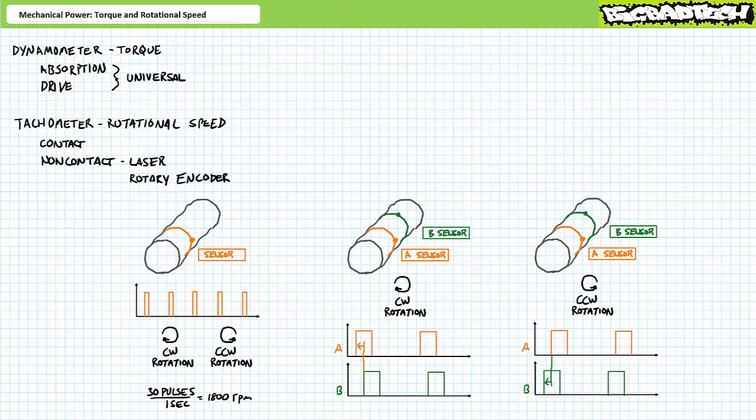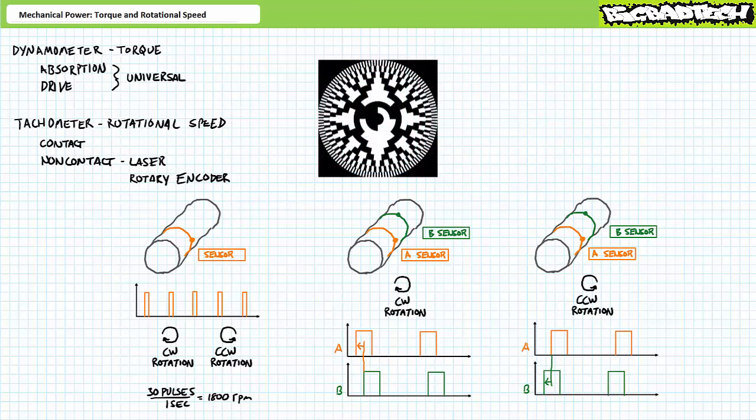There are varying levels of complexity of this type of rotational speed measurement, and is sometimes referred to as, quite surprisingly, AB encoding, incremental encoding, and/or quadrature encoding. We'll get to these methods much later. Much later, we might visit absolute encoding, in which each angular position in the shaft is assigned a specific binary address utilizing something called gray code, where only 1 bit position changes for each transition to the next position. For now, just think of these advanced methods as super fancy methods of determining not only rotational speed and direction, but also relative or exact position of a shaft.